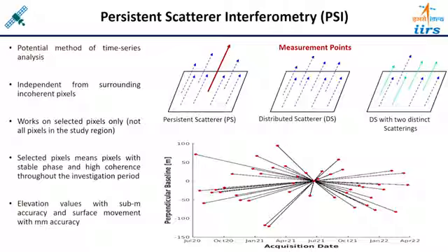So in that case, what will be the maximum temporal baseline? From here to here. That may be July 2020 to April 2022, so 20, 21, 22, almost 2 years. It means from here to here the temporal gap will be 2 years. It means there are more chances that the signals will be decorrelated, or you can say the coherence level is less. So automatically, the sum of coherence will be down. But the reference image wants the sum of coherence to be maximum.